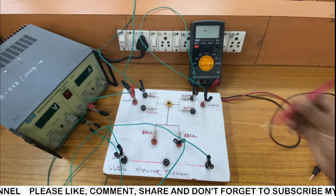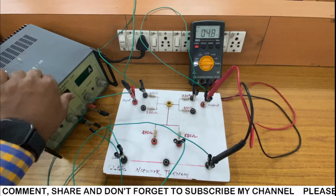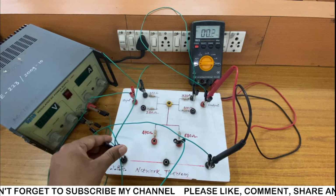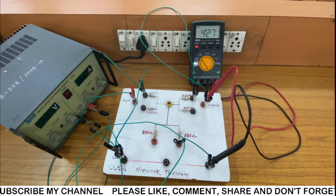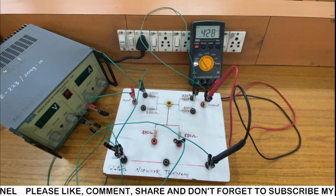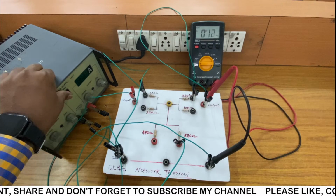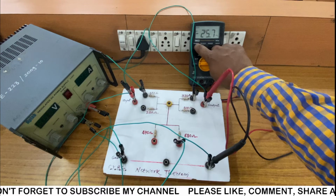What we are going to do now, we have calculated theoretically, we are going to practically calculate what is VTH. So look at here, the VTH is 4.31 volt and we are going to calculate RTH by just neglecting the power supply, shorting resistance R1 with ground. We are getting RTH to be 0.428 kilo ohm, so 428. So theoretically it was 417, practically it is 428. So we'll have a different reading in case of the maximum power transfer theorem as well. So that's why we are taking the step of 50 ohm.